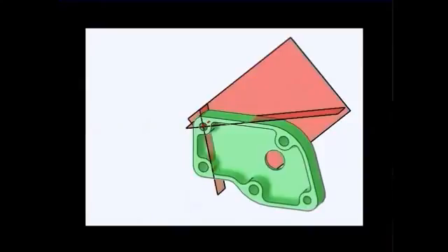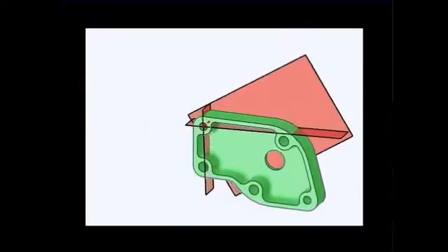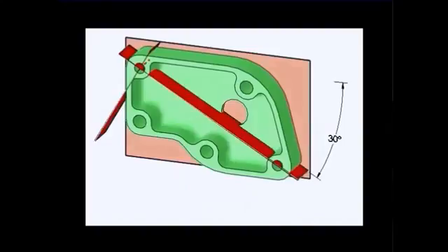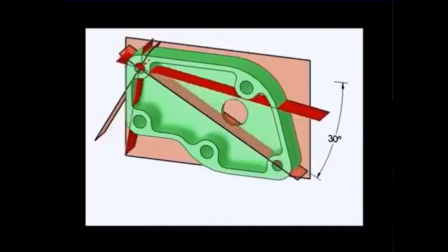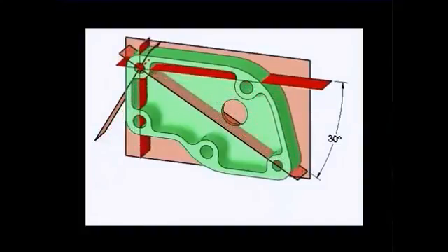So the intersection of your second and third datum planes will intersect at the axis of the hole. That's our datum feature B. And then we use datum feature C to orient the planes of the datum reference frame. Now this is awkward many times for measurement, so we've added a 30-degree basic angle, which allows us to have some auxiliary measurement planes. It doesn't add any tolerance to the drawing, it just makes it more convenient then to measure, so you'd rotate your setup 30 degrees.